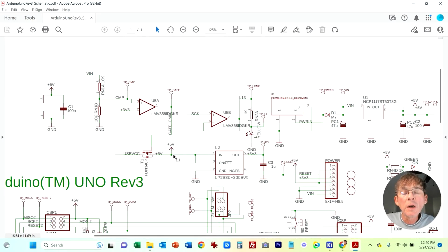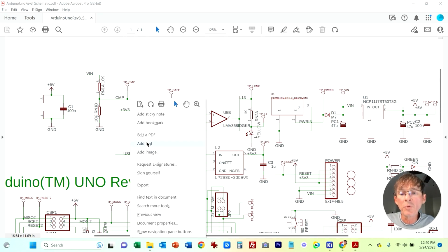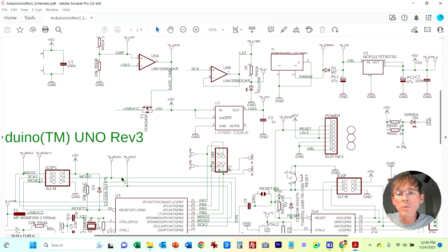Okay, they do not have a capacitor there. I guess they are just using this. Well, keep in mind this 5-volt supply already has this little 100 nanofarad, and it's got this 47 microfarad, but these are only if we're powering it from the main power input, not through the USB.